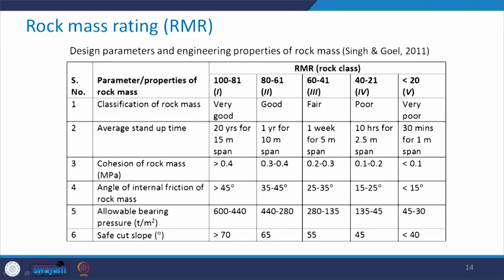See here, as I explained, 20 years for 15 meter span. It should not be that we wait for 5 years to provide the support system because the stand up time is this large. No, as soon as we excavate and it is convenient, convenient in the sense of the construction activity, immediately we should provide the necessary support system.